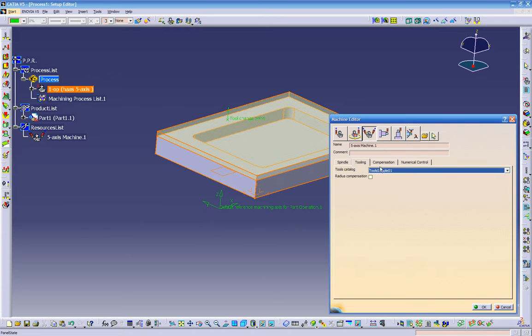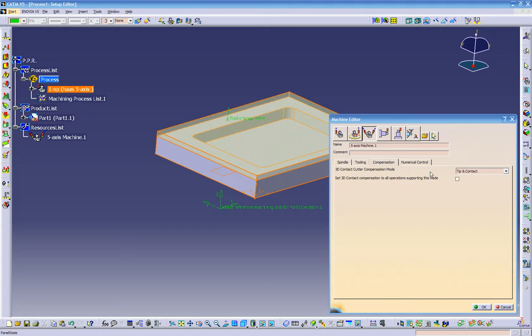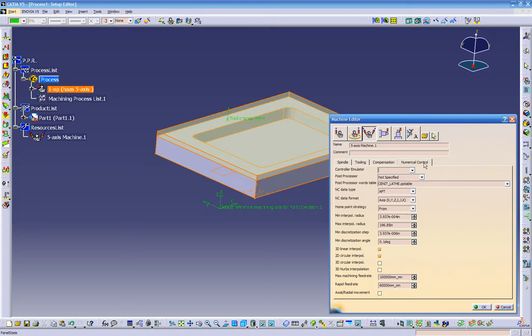And I'll show you in a minute what I mean. I'm going to give you my own library, so you don't have to use the sample one. It's already built up if you feel comfortable. Over here we use the cutter comp. So if you use the cutter comp, you turn it on over here. You have to turn this off first. So this is the cutter comp in here.